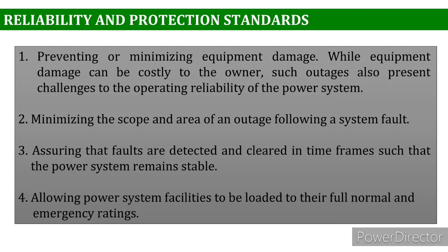Allowing power system facilities to be loaded to their full normal and emergency ratings. For example, students, operation designs of bulk power systems are such that at minimum the system must remain operational upon the sudden or unexpected loss of any single facility on the system.